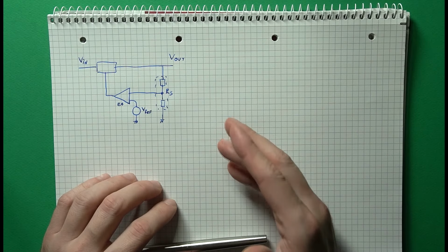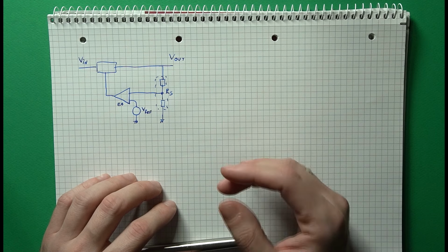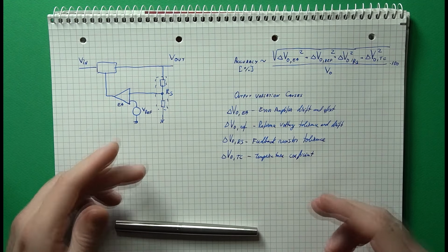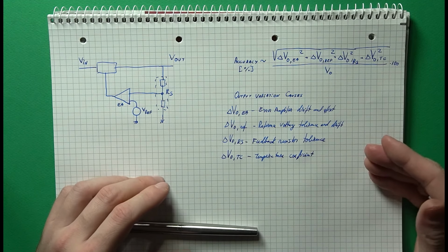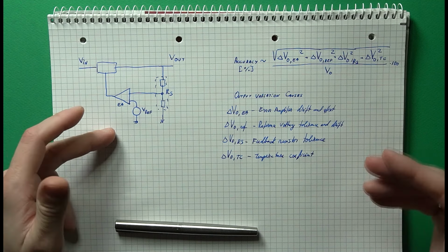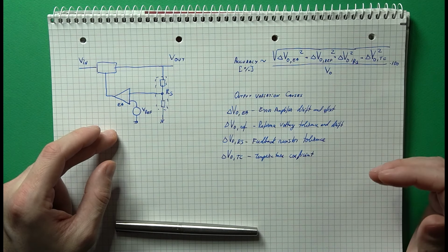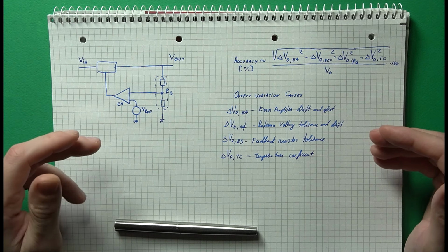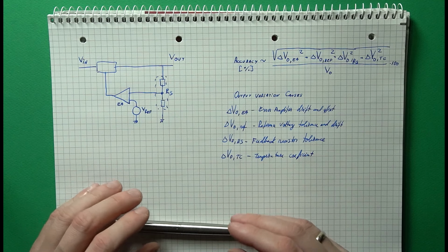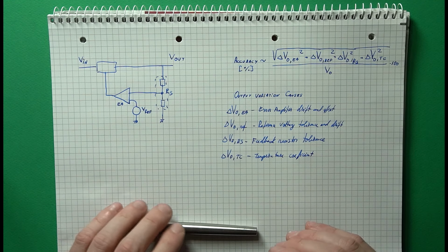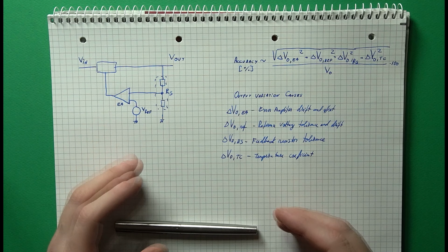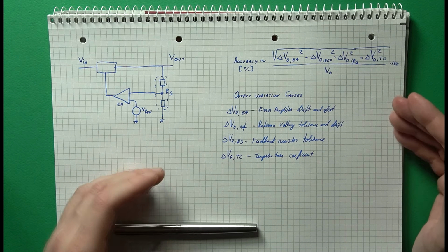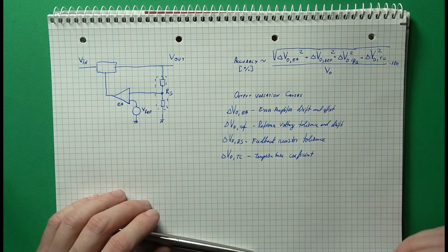Now, the reason why the output may not be the exact value that you expect is because the control circuit is not built from perfect components. So the feedback resistors will have a clear initial tolerance, the voltage reference has a specific tolerance and a drift in time, the error amplifier has an input offset as well as a drift, and all components and circuit bits are temperature dependent. So the various elements in the circuit will have a specific effect on the output accuracy, and the total accuracy can be calculated based on all of these effects combined.